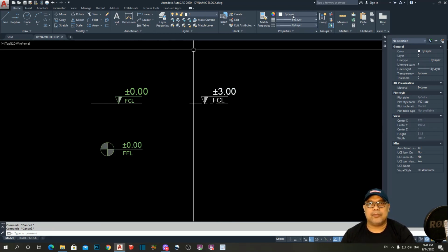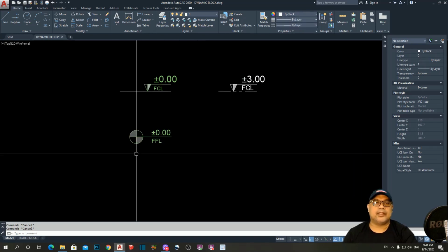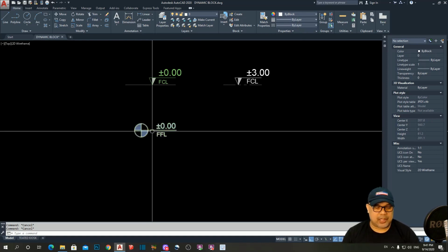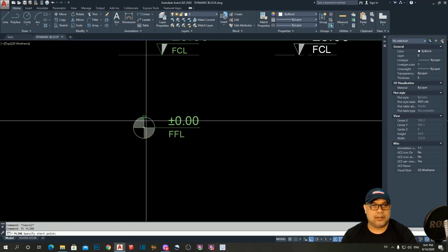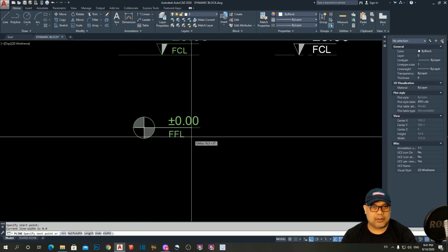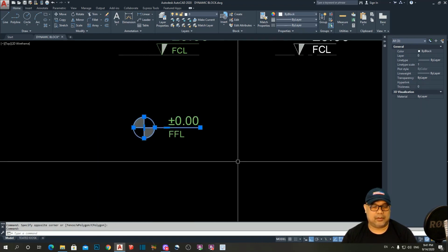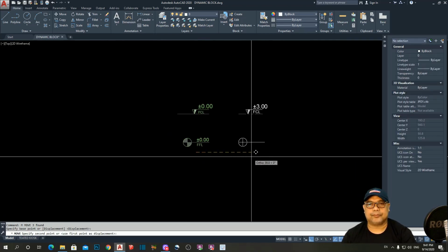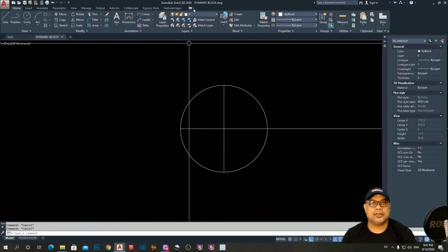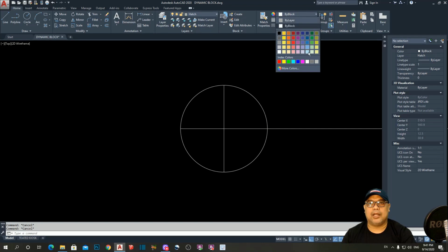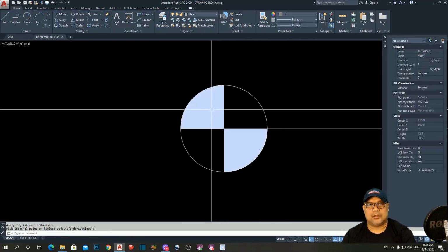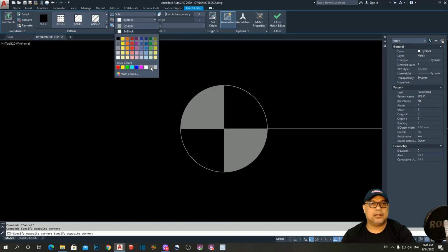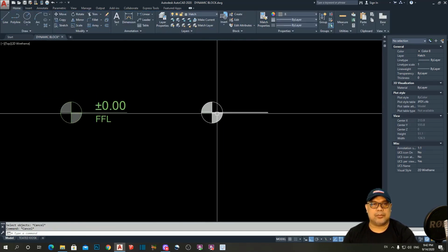Okay, again I have to put this one by block. Then let's try. Okay, again to save time, I have to trace this one. Okay, in here, then this one in here, then this one in here. Okay, then I have to fill this one with solid hatch. I have to go again to the hatch by block. H is the shortcut for hatch here, then enter. Then I will put this one as by layer.